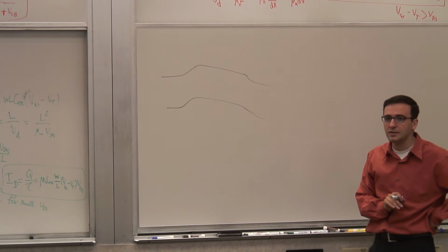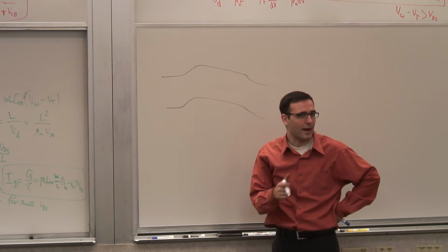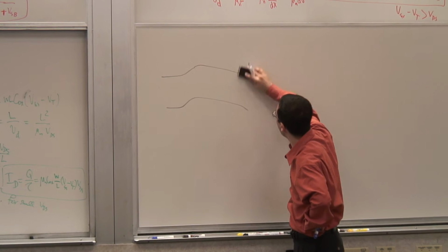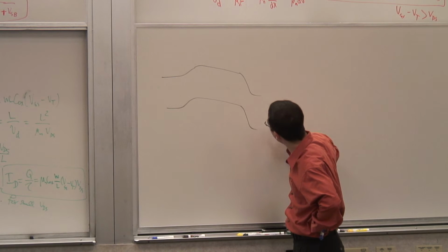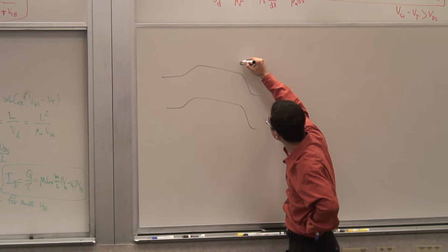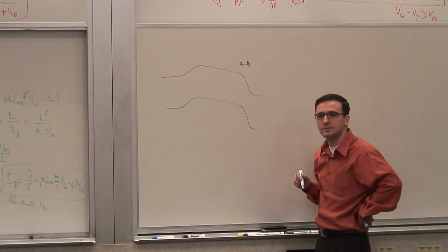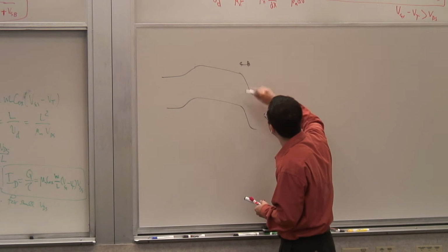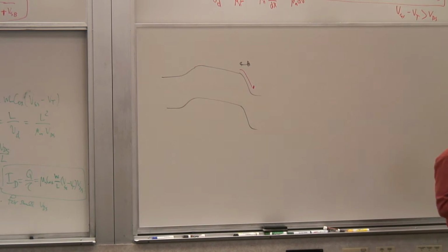Now, if I apply a large VDS, this channel, this part, is what controls how much current will flow. If I apply a large voltage, we saw that beyond a certain point we have pinch-off, and most of the electric field will fall across this pinched-off region. And of course, any electron that makes it here will go down the slope. That's not a problem.